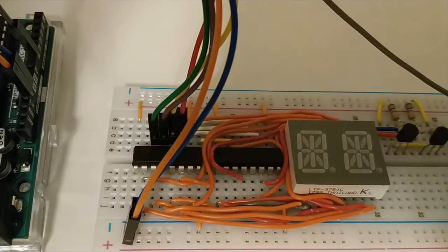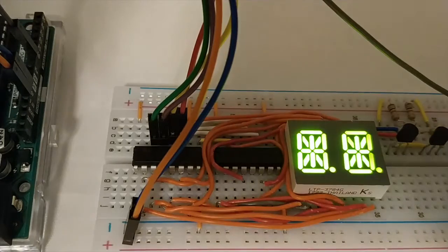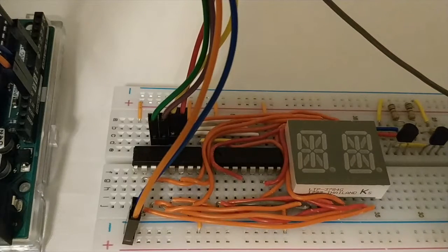When a user enters two English letters, they will be echoed on the display. Once the characters are processed, the letter's segment data is called and shifted out to the registers. They then present highs or lows on their output pins, illuminating the correct segments and displaying a letter on the display. It is impossible for both digits to display different information at one time.